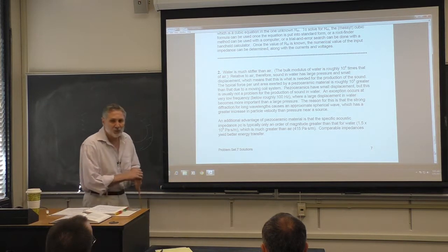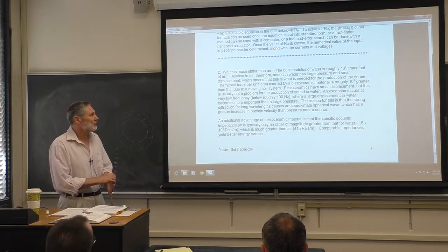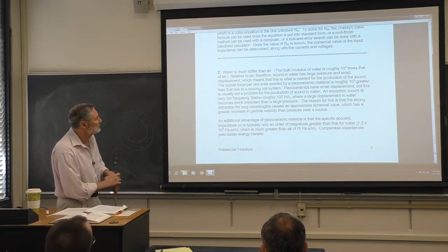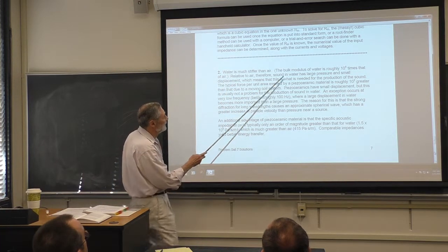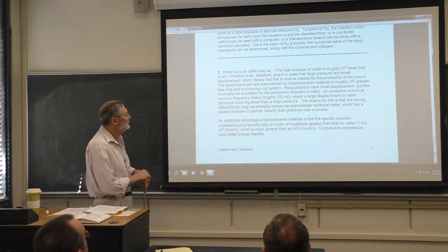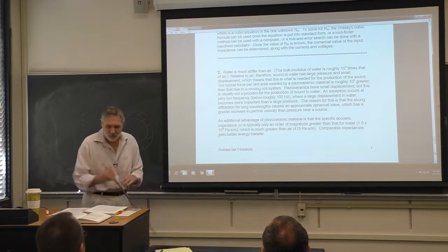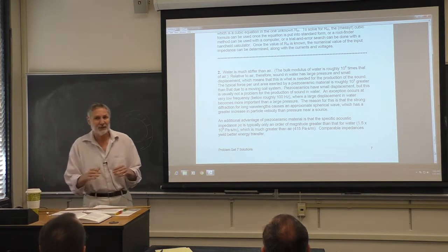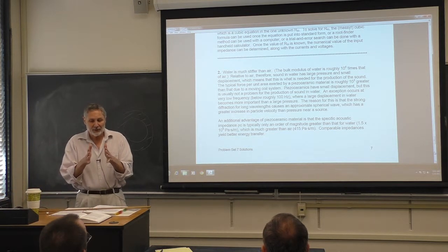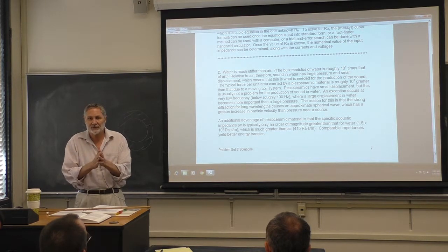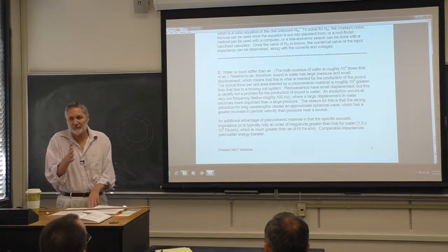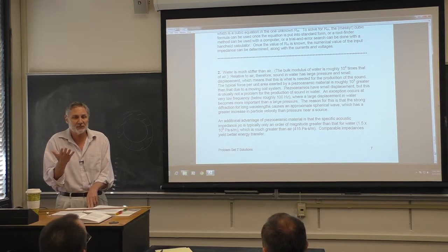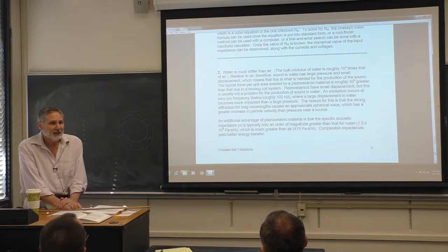So why do you want to use piezos for water and loudspeakers for air? Well, that's the purpose of this problem. To begin, we know that water is much stiffer than air. In fact, the bulk modulus is about 10,000 times that of air. As I've mentioned many times before, starting last quarter, in water, relative to air, you have small displacement but big pressures because it's so stiff. So the sound will have that characteristic, and you want whatever creates the sound to have the same. That's what piezos have. They can generate high pressures but not much particle velocity.